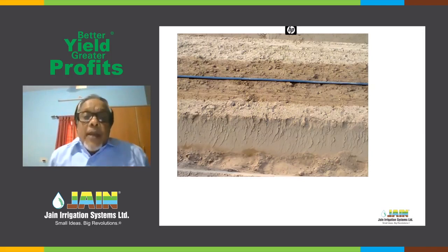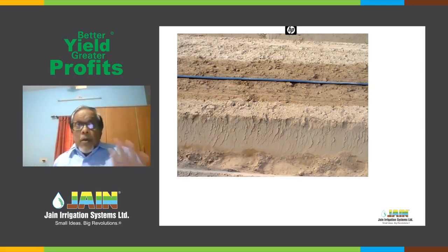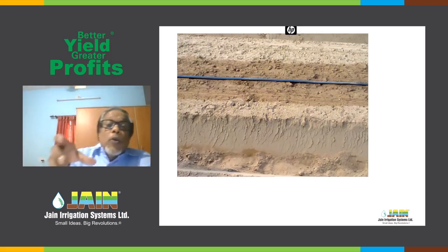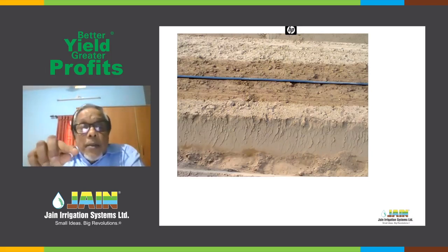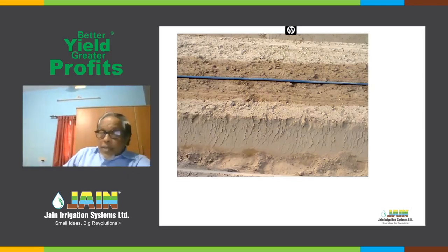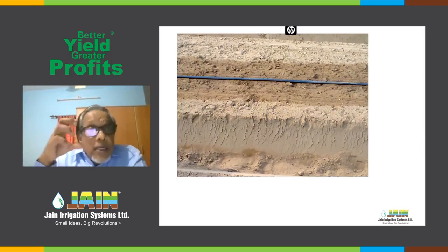So this is to say, when you take a decision based on the soil type, the lateral to lateral spacing and dripper to dripper spacing and the dripper discharge rate, all three, I clearly explained in the last webinar. Based on the soil type and the crop plant rows, in your scheduling and the application rate also, you have to intervene and help the farmer to understand it. In any case, the irrigation schedule will be lower amounts in the just germination stage and early stages, and higher amounts when the peak growth comes in. That is true. But that is the total volume.